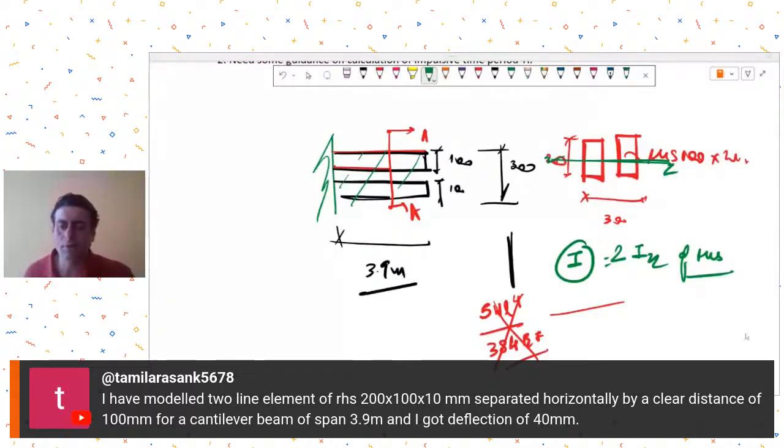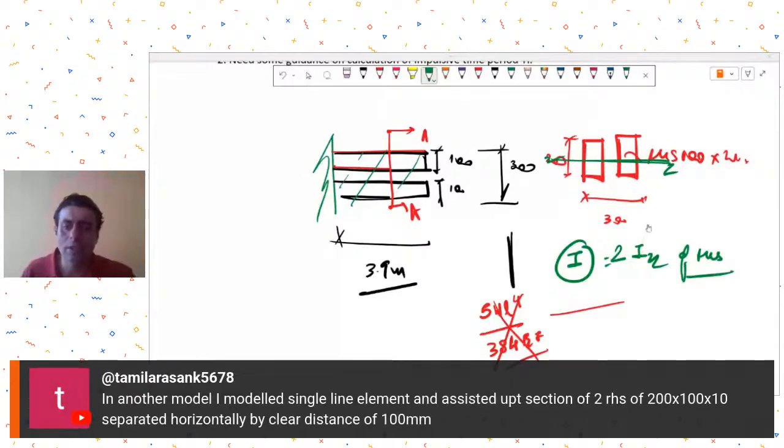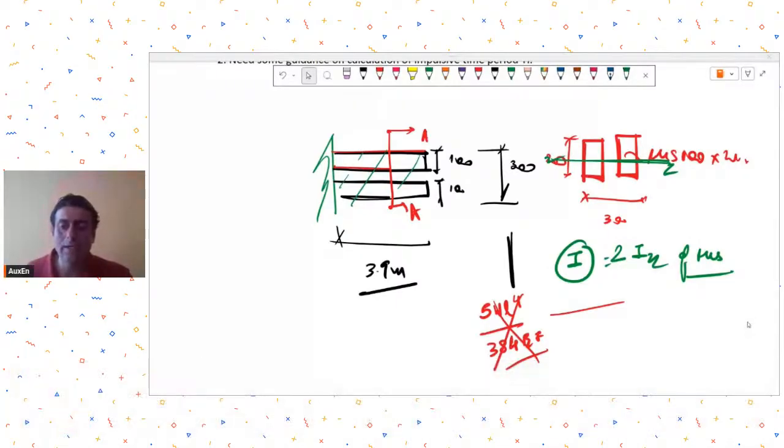Using manual calculations, just check what deflection you are getting. From that you will get an idea whether your normal STAAD assignment is working or your UPT calculation is working. Very easy to check. Because there is such a large difference, the mistake you are committing is that while bringing it from UPT to STAAD, the section modulus values have to be interchanged by the user, because there is an axis reorientation that happens. So just check that. Because you are getting almost three times difference, I think that is what is happening.